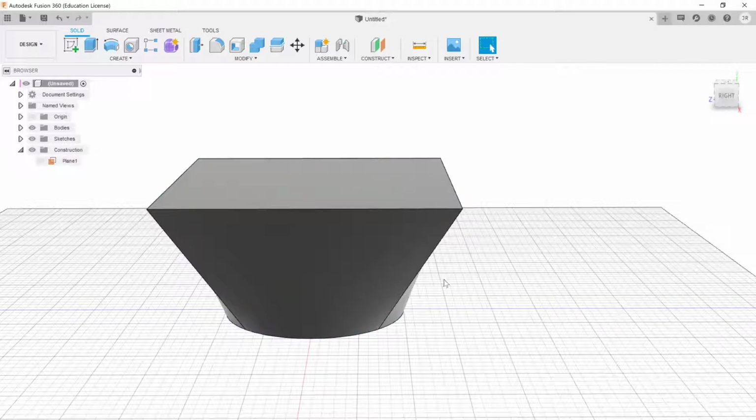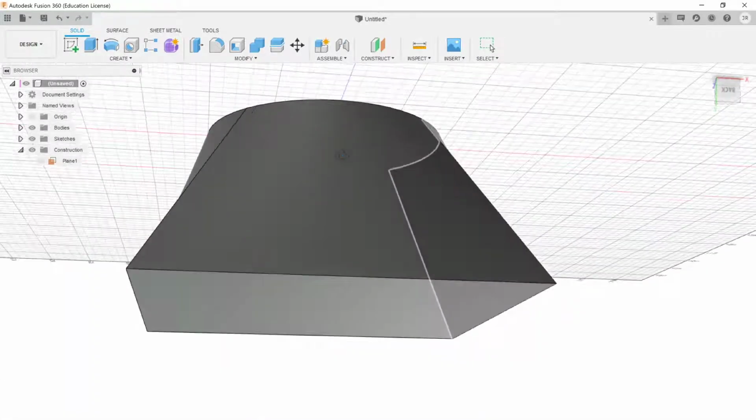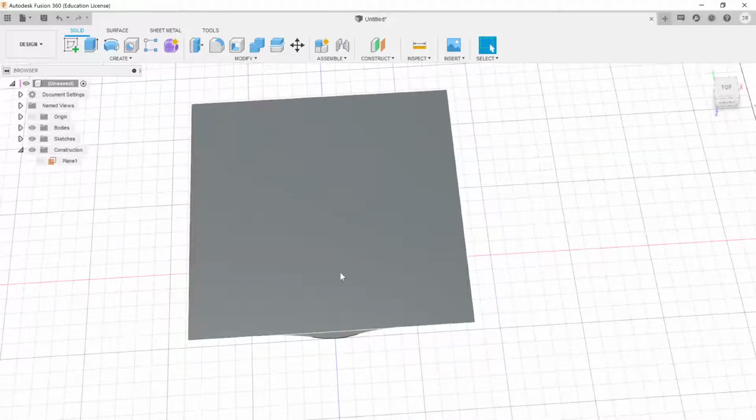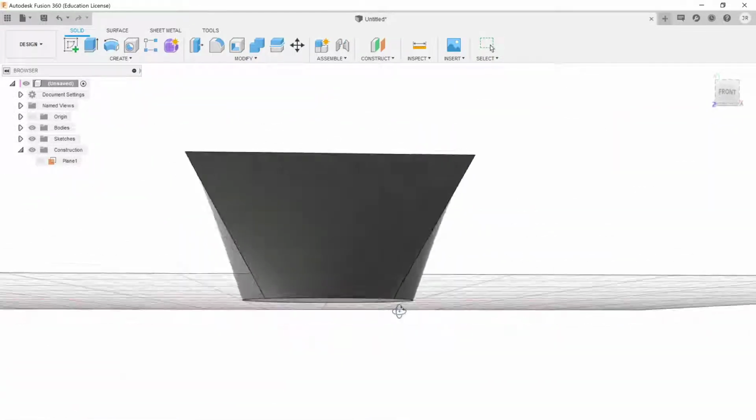So there it is. And so the result is a nice smooth transition. You can see that it starts off round and it figures out this shape automatically. So if I made a more exotic shape, then the circle would have to adjust to it. Any two sketches can be lofted between each other. Now, that said, if the shapes are really odd, then maybe we have to be careful because the loft might warp and pinch and not look correct. But it is generally a useful tool to make these blend smoothly.